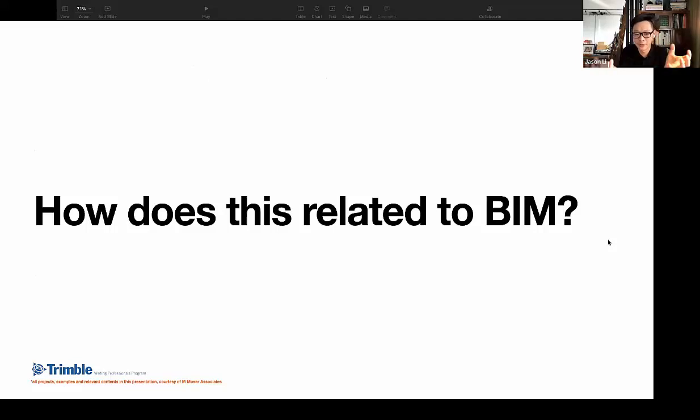So it's two different pieces of software, right? And the initiation of BIM is actually we want to use the model to drive the rest, right? Regardless of whether it's 2D documentation, a 3D model, 4D virtual design construction, or 5D quantifications and all that. So everything is stored in a 3D format, and thereafter the 2D is just deriving a 2D documentation from the 3D model, right?